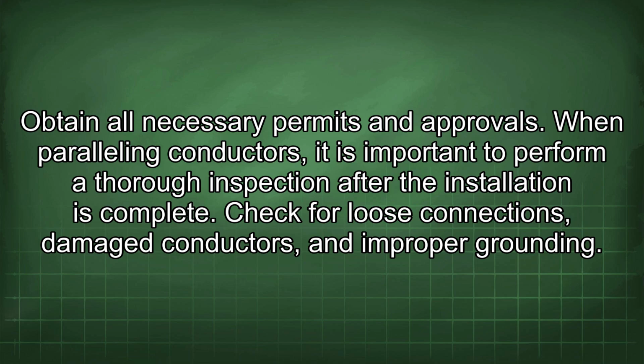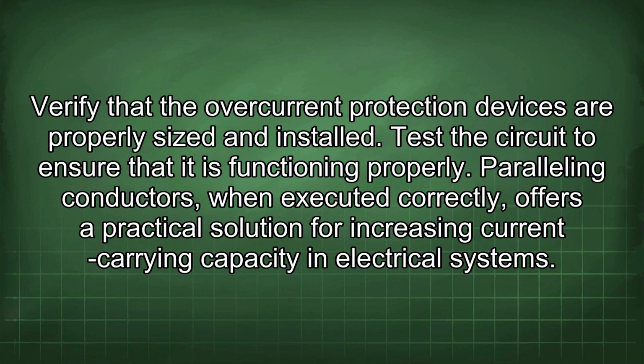When paralleling conductors, it is important to perform a thorough inspection after the installation is complete. Check for loose connections, damaged conductors, and improper grounding. Verify that the overcurrent protection devices are properly sized and installed. Test the circuit to ensure that it is functioning properly.